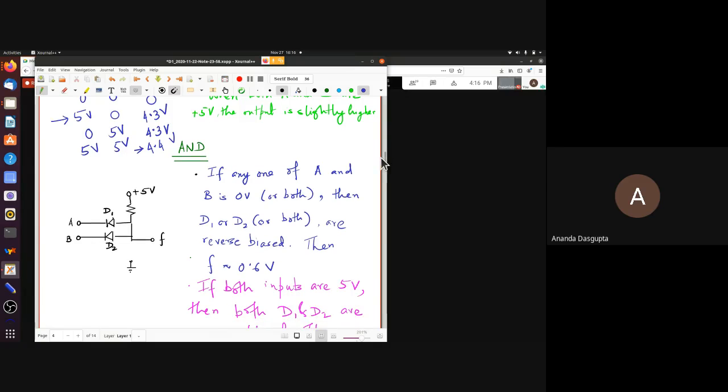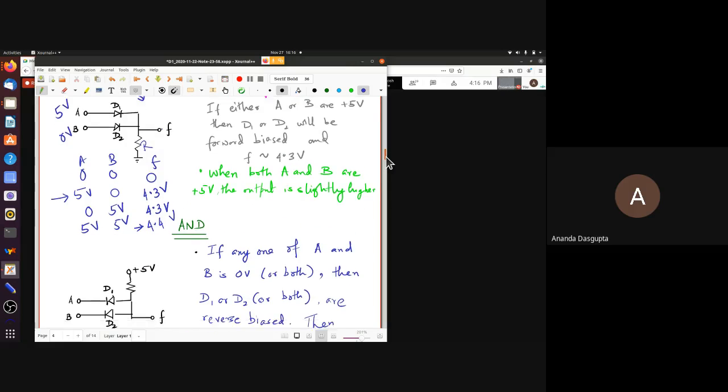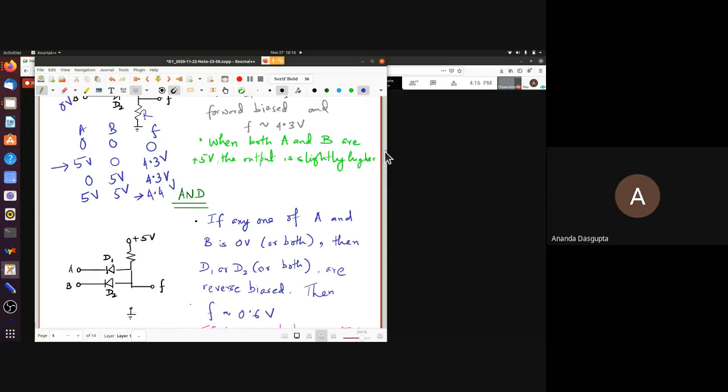Okay, how do you make the AND gate? Well, the AND gate is similar, except that the two diodes, if you compare the OR and the AND, they're hard to see both together. But one thing, the diodes have been reversed. They're now pointing towards the input, the arrows at least. And the resistance, instead of being connected between the output point and the ground, is actually connected between output and plus 5 volts. And every voltage, of course, is measured with respect to some ground, which is not directly connected to any of these components, but will be connected via whatever source you connect.